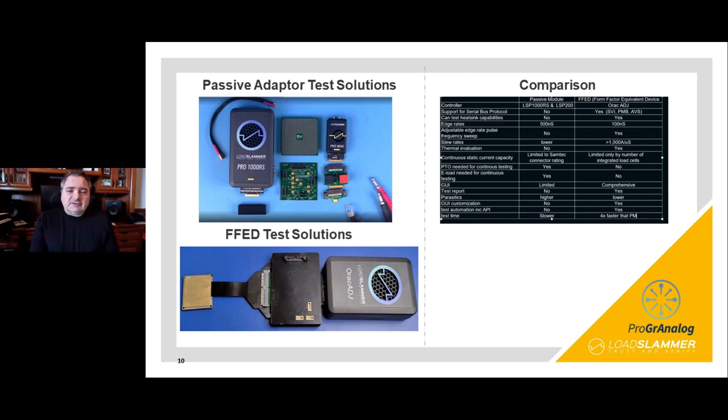If you need to do continuous current or OCP testing, then you'd add what we call the PTO, which is the red and the black cube on it. And then you can see some cable tips at the end that would plug into that. And that allows you to connect the top of the passive module to an electronic load in your lab. So you can do additional constant current testing as well, so stress testing your OCP or just getting a basic efficiency measurement.